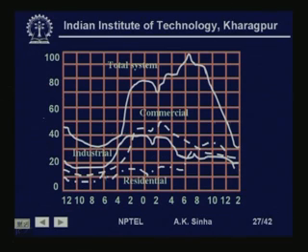This is what you are seeing as a residential load, that this loading becomes much larger during the evening when people have switched on their TVs, they are doing their cooking and all that. So, all lights are on and so on. Whereas, if you see industrial load, it will be very high during the daytime. Commercial loads again are high starting around 10 o'clock.